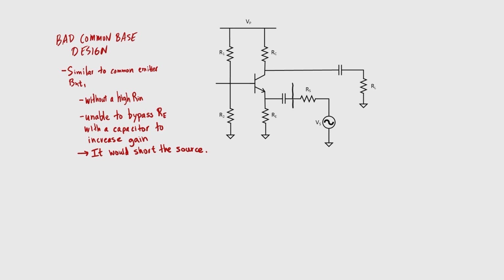What is the input impedance of our common base configuration here? Well, if we assume an emitter resistance, little r sub e, and then we use impedance reflection to bring these two resistors at the base over to the emitter side by dividing them by beta, then we'll end up with an input impedance of R sub E in parallel with little r sub e, which is in series with the resistors attached to the base divided by beta.